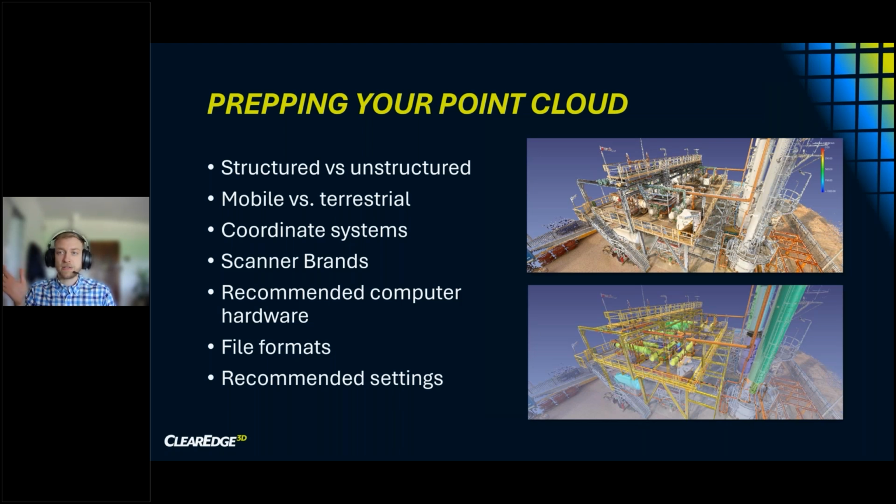And then effectively, as long as that coordinate system is saved to the point cloud, which is very important and recommended anyway, you don't have to deal with transforms when moving projects around. You can just drop the point cloud in. That works great with EdgeWise. So it's highly recommended that you spend some effort and time getting coordinate systems figured out, and that's true regardless of your workflow, outside of EdgeWise or otherwise.